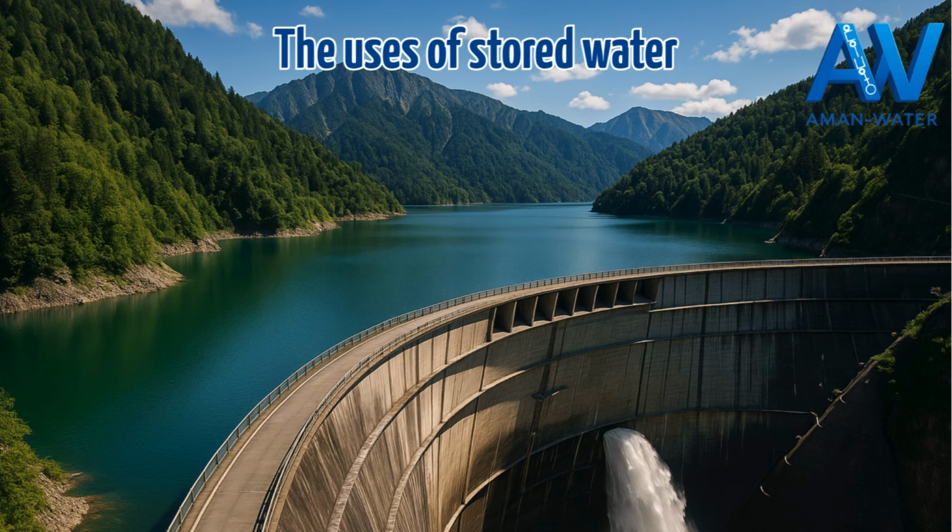The first use is drinking water. From the reservoir, water is taken at different depths, where quality is most stable. Suitable intakes avoid surface layers, often warmer or more loaded with organic matter. Once captured, the water goes to treatment plants before supplying cities and villages. During dry periods, the presence of a dam ensures continuous supply even when the natural river weakens.